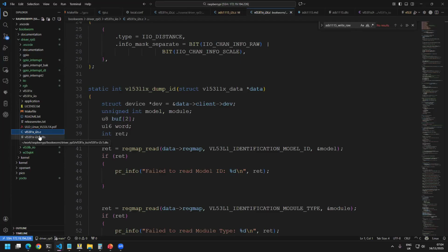Photons go and hit some object, and then come back and are received by the photodiode. And since it's a laser, which is light, we know the speed of light. And when it went and hit the object, and when it came back, we know how much time it has taken. So based on that, we calculate what's the distance of that object. Internally, it has a firmware.